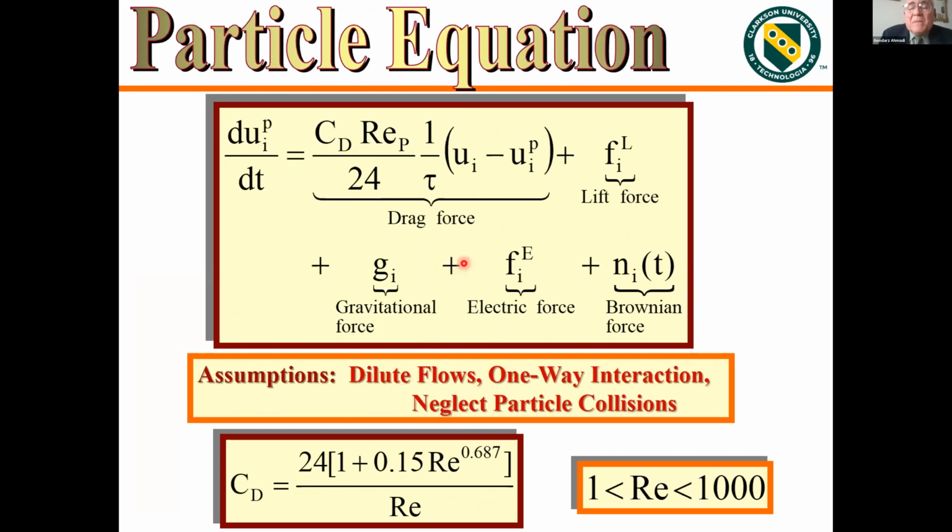And in most situations, the particle concentration is not very high, so we can use so-called one-way coupling. We do the flow, and then we trace millions of particles or more, whatever is needed to get our accurate estimates. There are some details here which we'll skip, on how to evaluate these forces correctly.